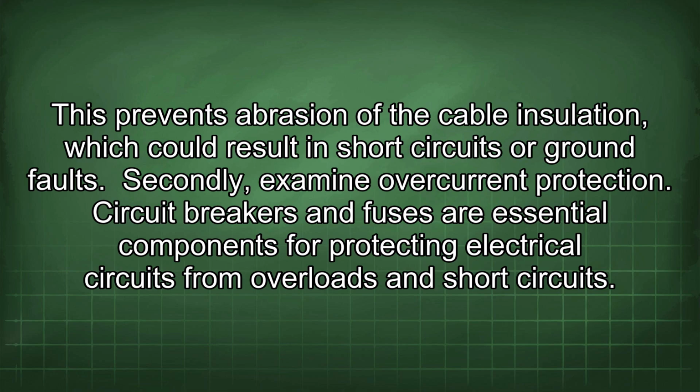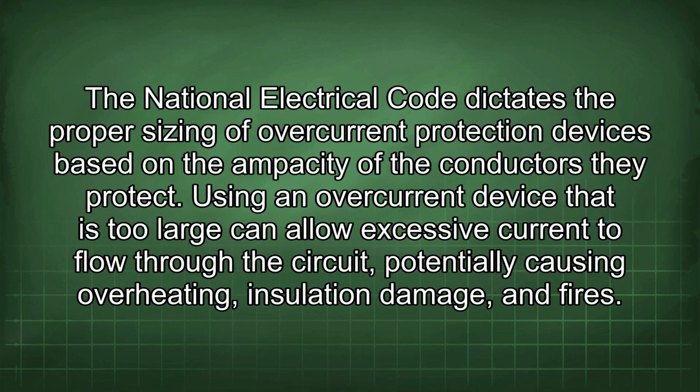Secondly, examine overcurrent protection. Circuit breakers and fuses are essential components for protecting electrical circuits from overloads and short circuits. The National Electrical Code dictates the proper sizing of overcurrent protection devices based on the ampacity of the conductors they protect. Using an overcurrent device that is too large can allow excessive current to flow through the circuit, potentially causing overheating, insulation damage, and fires.